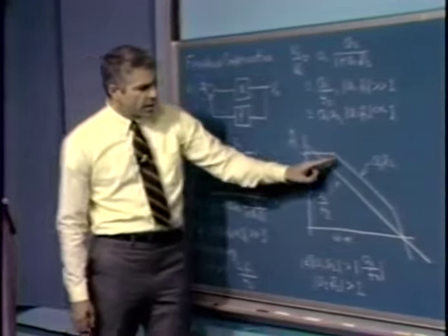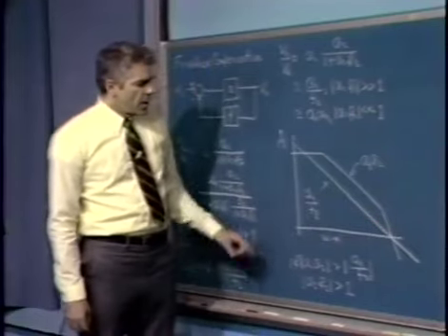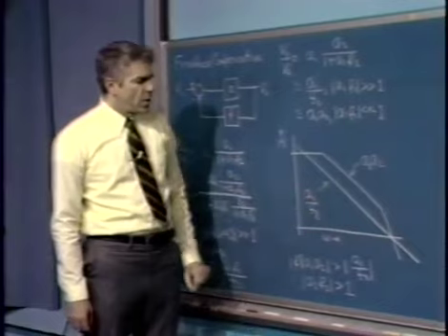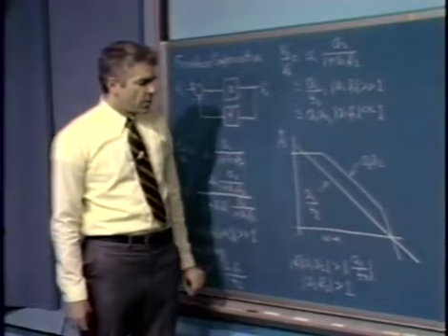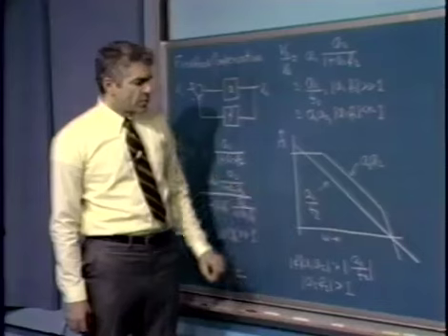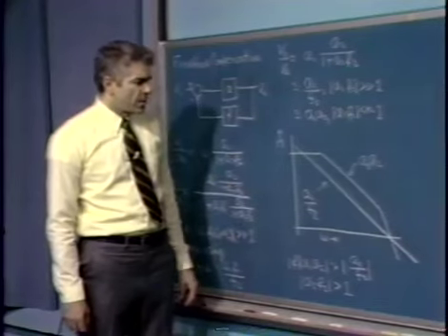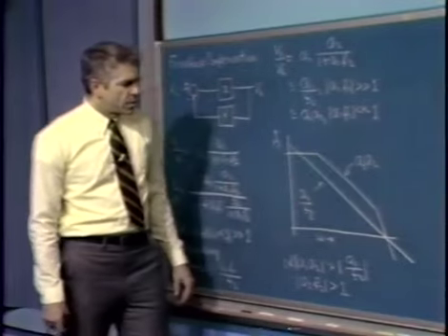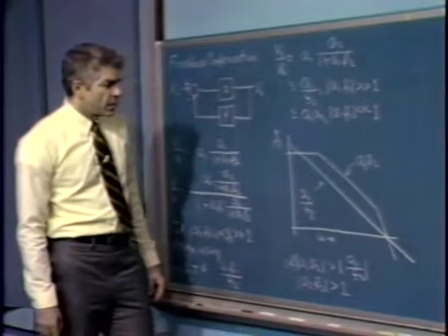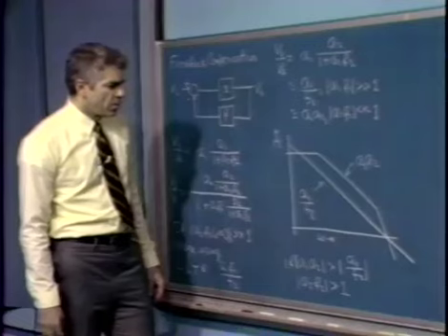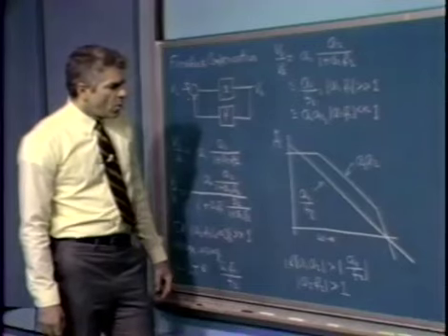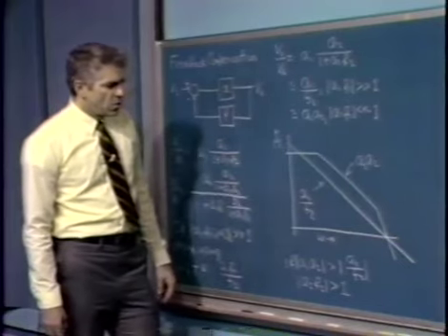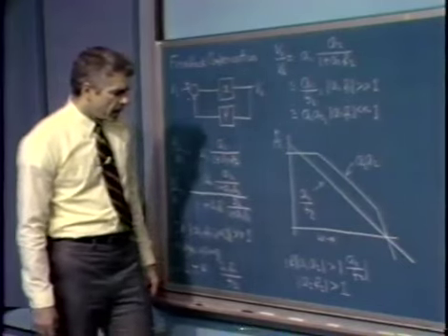Well, once we've plotted these two transfer functions, in particular the two limiting approximations, A1 over F2, which is the approximation that holds when the loop transmission of the minor loop is large compared to 1, and the A1, A2 product, which is the approximation that holds when the transmission of the minor loop is small compared to 1, we can very easily determine which of these approximations holds at any given frequency.